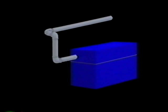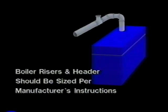We'll begin with the supply tapping. On most Weil McLain boilers, the tapping, or tappings, will be on the top of the unit. However, on some boilers, the supply tapping may be found on the face of the sections rather than the top. The boiler risers are connected to the header. It is important that the header be sized per manufacturer's instructions, never less than the recommended size.